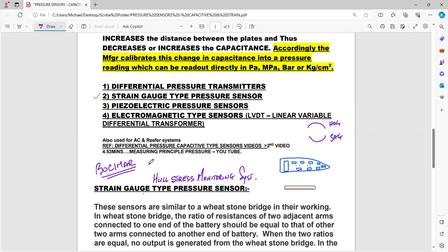And therefore, when they ran into that severe cyclone, that stress caused the ship to hog or sag excessively and break in two. And that's why it sank. All hands lost. Okay, had they had this hull stress monitoring system on board, possibly they may have saved the ship, because it gives you the stress on the hull even whilst loading or whilst discharging.